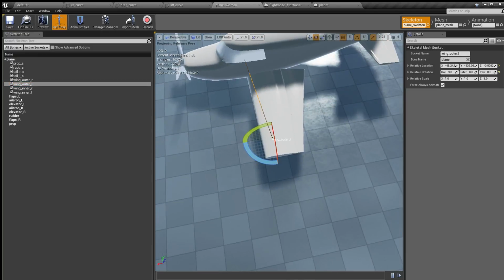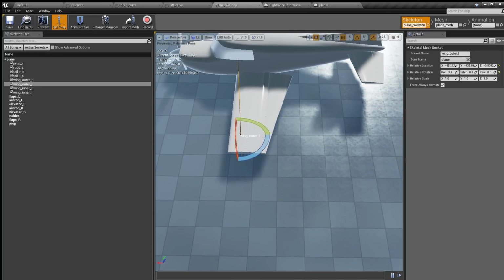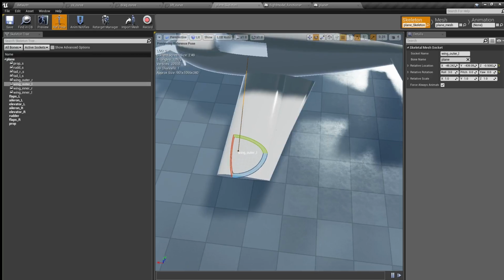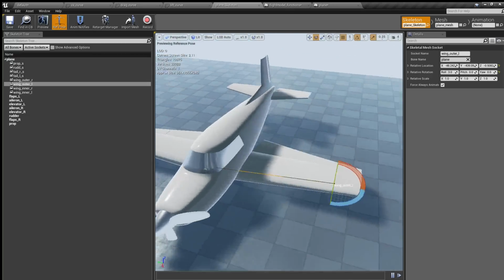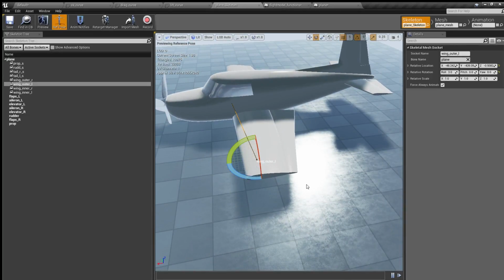This is known as center of lift. In reality, this location shifts with increasing velocity, but this is only relevant at speeds approaching Mach 1. So for general aviation aircraft, fixed location is good enough.